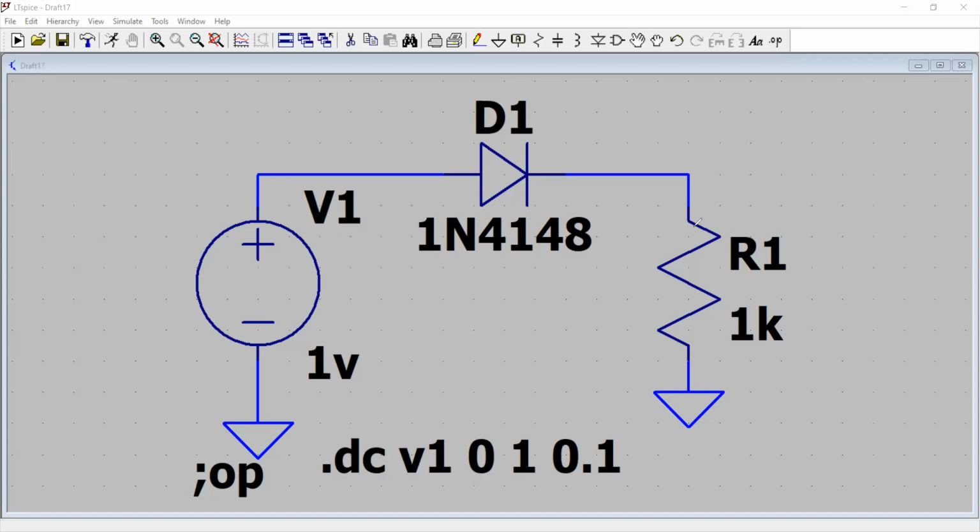So today's topic is about understanding in more detail the behavior of a diode, which is a PN junction, and we'll see the current voltage relationship of a diode. And we know that in our previous discussion, we've seen that the current and the voltage relationship of a diode is given by such a curve, which is an exponential behavior.